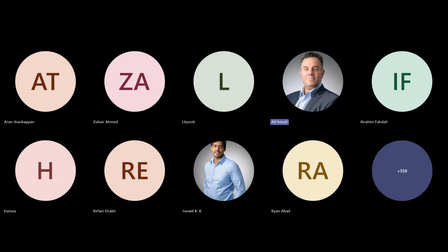Need more clarification on IFC. False ceiling: it is included. There is a class in IFC called IfcCovering. So you can use it to model the false ceiling and bathroom and kitchen fixtures.